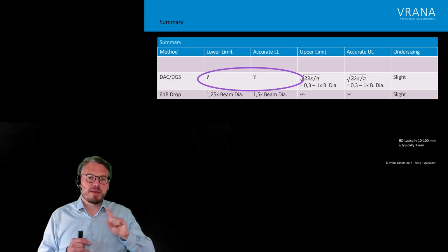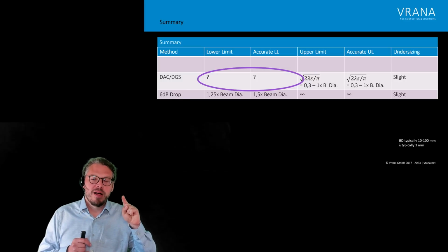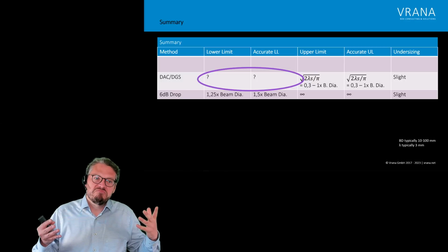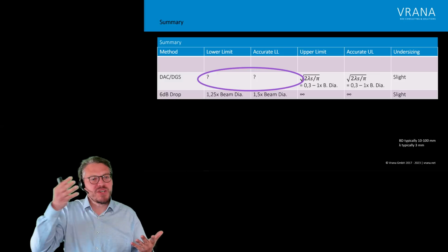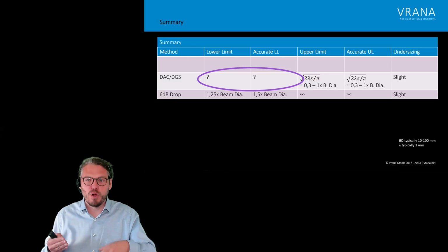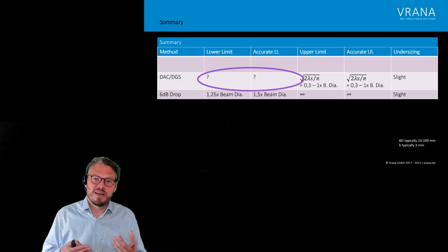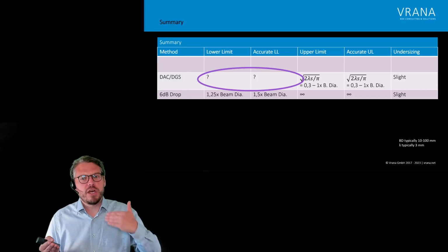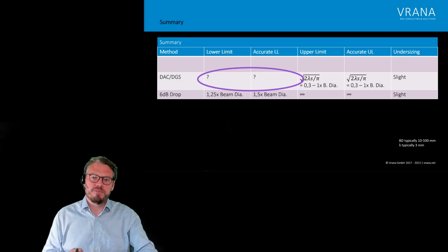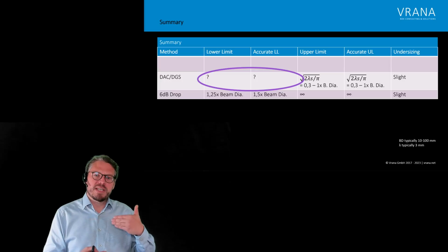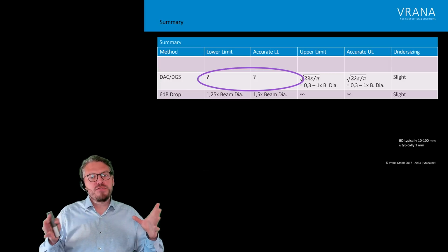But actually, and that's something we will see within this video, a small flat bottom hole isn't really a good model for a real defect. So we cannot take a flat bottom hole for an experiment for a small reflector. We would have to use real indications. But on the other side, real indications we cannot really bring into the components. And if they are already in the component, then we would have to measure them first. But do we know that the measurement is accurate? So experiments are at least very complicated, if not even impossible.